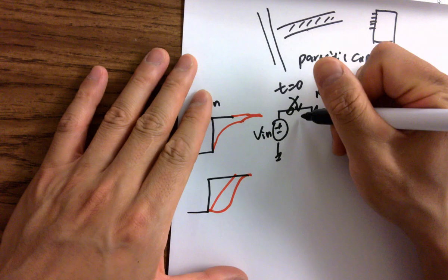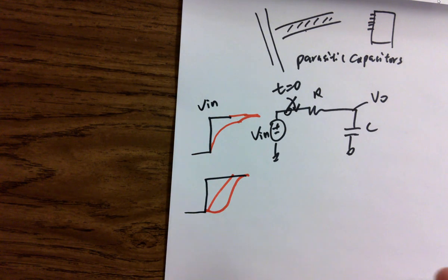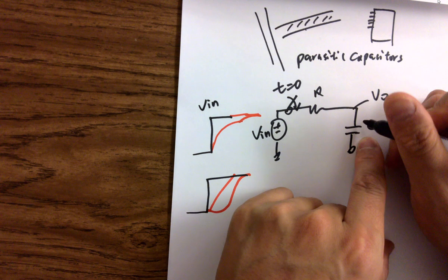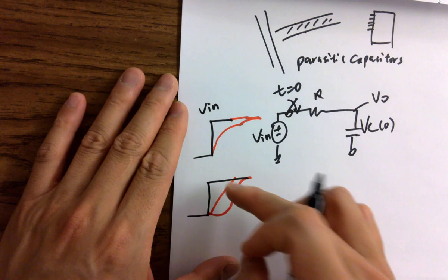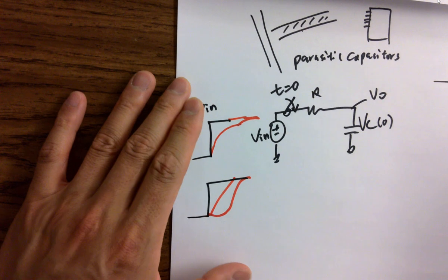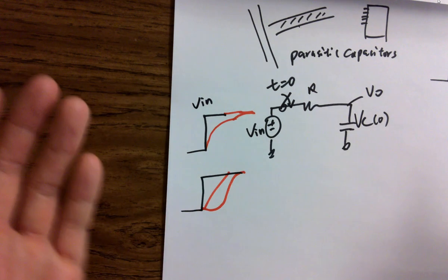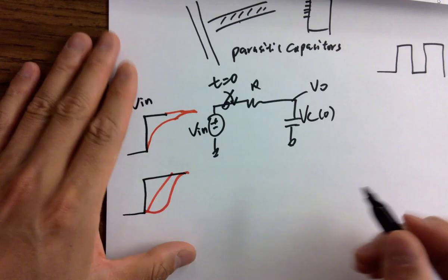So when you close a switch, there are different conditions, right? But not too many, because we don't have 3 components. How many conditions can you have? Not too many. So we can assume that there is a VC0, okay? The initial voltage being stored in the cap before we close the switch. But it shouldn't happen in digital circuits because we have oscillation, we charge and discharge. When you discharge, everything is discharged, so we shouldn't expect any charge. But let's just have a general case, and we write an equation.